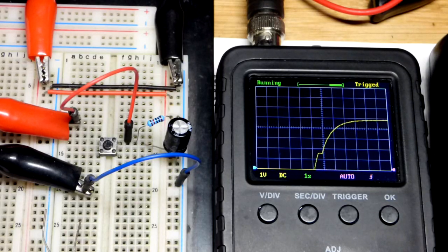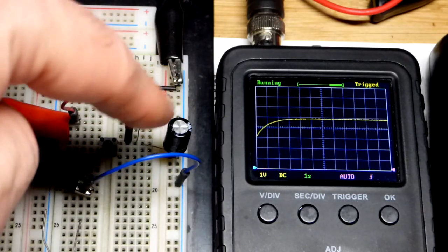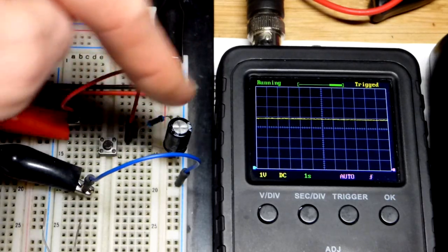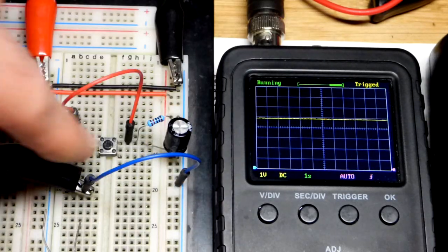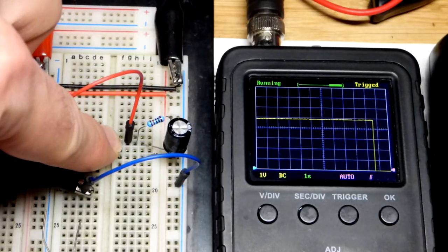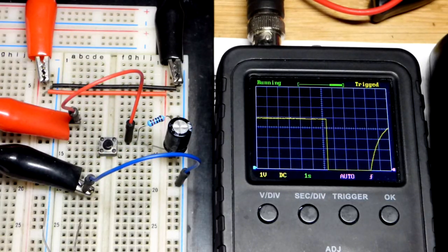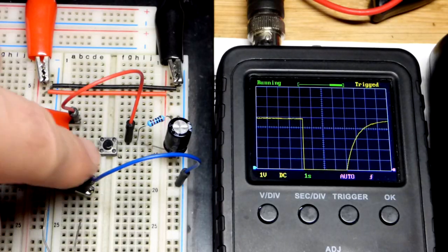And you can see a curve, of course, because with capacitors, their voltage rises based on how much current is going into them. As they get closer to the supply voltage, there's less voltage across the resistor, less current, and thus it charges slower. But in any case, I'm going to press the button, and same thing. This is our starting point. We're interested in this curve for the purpose of this video right there.